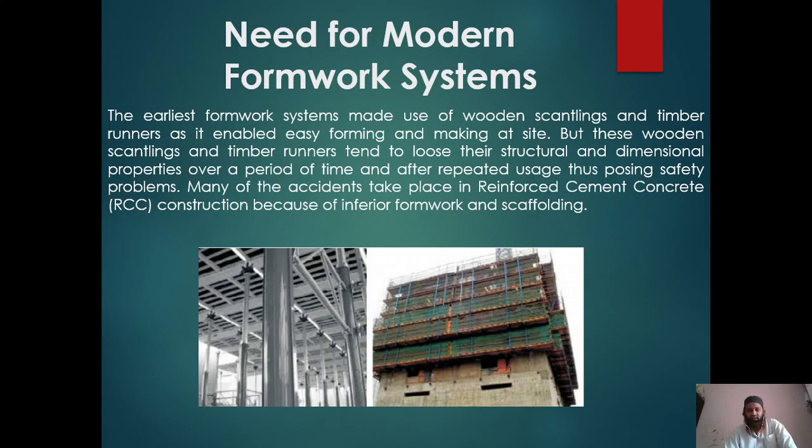But timber formwork tends to lose its structural and dimensional properties over a period of time and after repeated uses, thus posing safety problems. Continuously after using these timber and bamboo formworks, they lose their strength, and so this leads to unsafe conditions at the site, thereby increasing the number of accidents. So we should come up with some system of modern formwork where we can eliminate all these accidents caused by conventional formwork.